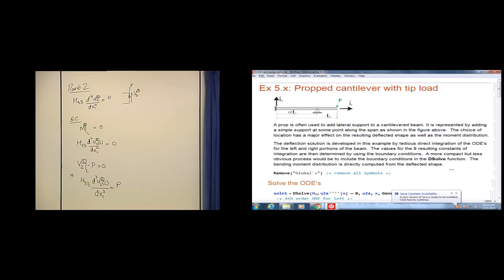I think moment is negative. Moment is negative of this, but because we have a 0 sign there, the negative sign went off. And then the shear force is negative of moment. So dM over dx1 is equal to minus V. So I think it's correct. Okay. So we have boundary conditions at.